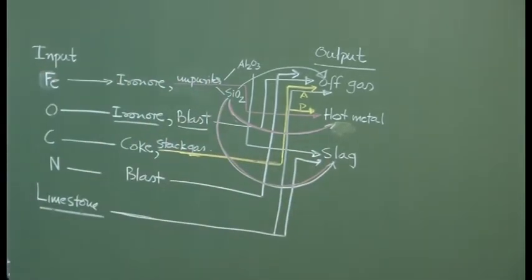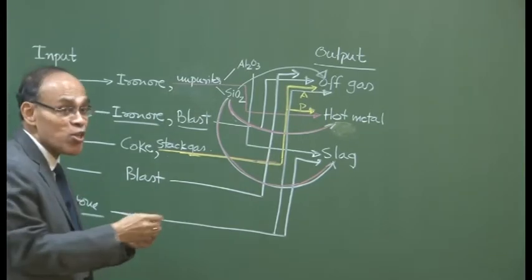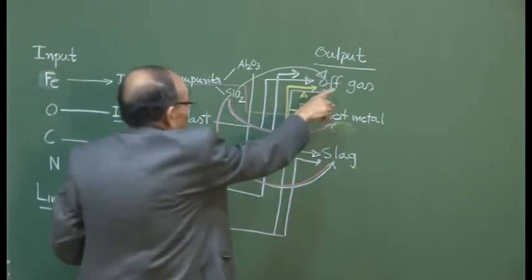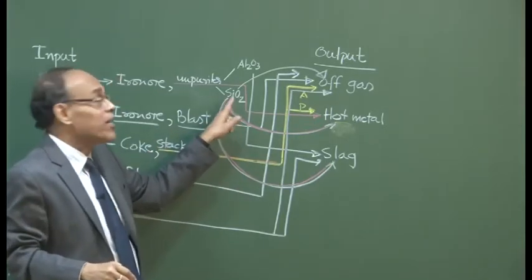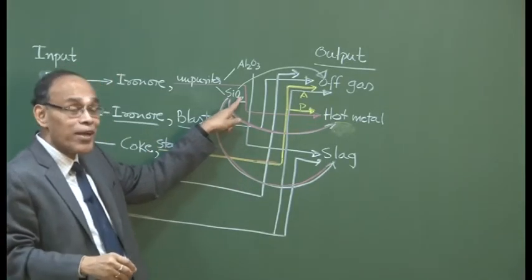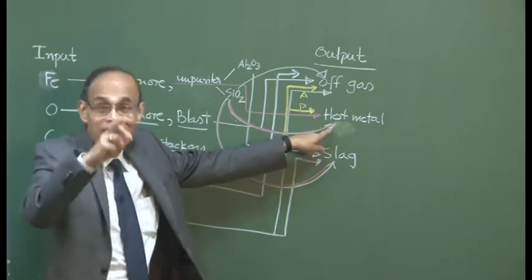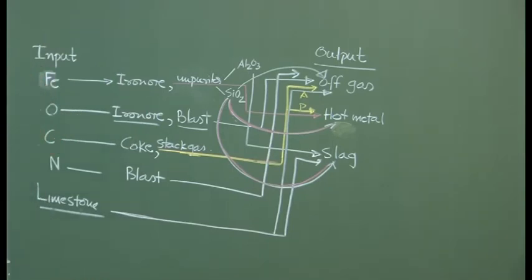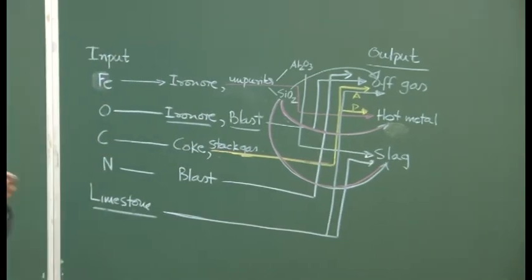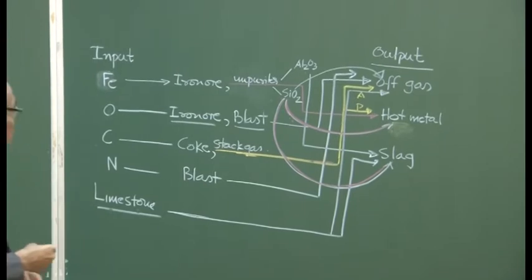as dissolved silicon, and in the process what happens is the off gas composition has now got disturbed because of the simple fact that oxygen has been liberated, and that oxygen which has been liberated because of this metalloid reduction reaction has now manifested in the off gas, and as a result of which the CO2 ratio has now changed in the furnace.